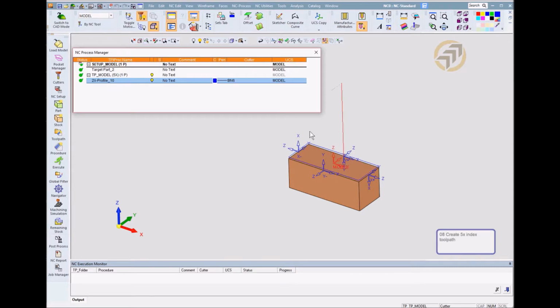Okay, to create the toolpath. So this toolpath will test, test for what? It is used to test whether the operator has set up the part 0 point, the work offset correctly or not, or whether the tool length is correct or not. By this profile we can know, testing this profile on the machine.